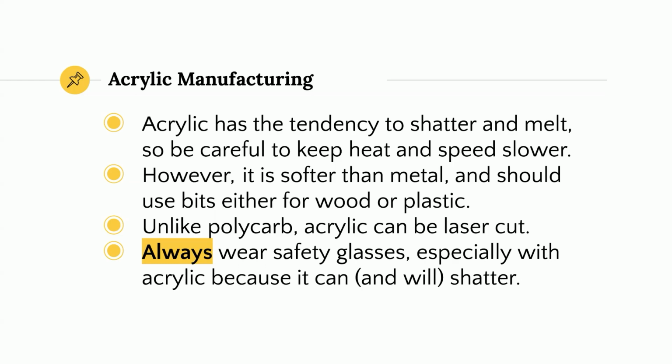So when you bring the miter saw down too fast with acrylic and you're not properly holding it down, it has a tendency of shattering and having shards of acrylic flying everywhere, which one of them knocked off of my safety glasses. I would be blind in one eye right now if I weren't wearing them. Please always wear safety glasses and be mindful of the shattering.